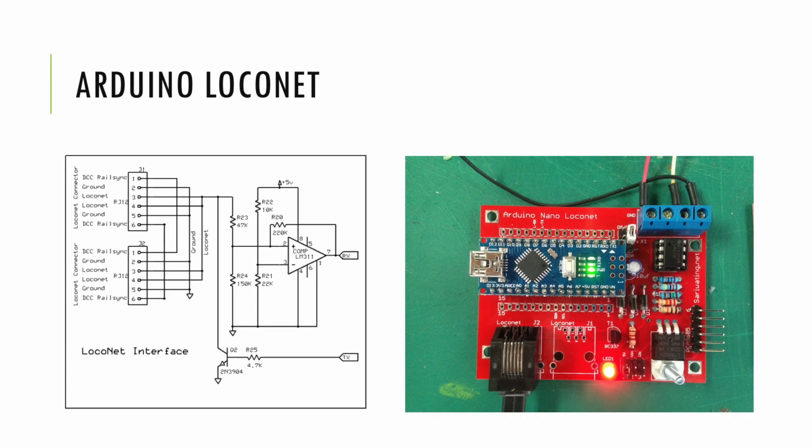We can easily connect an Arduino to Loconet and write some code that receives the occupancy detection messages from Loconet for the brake and stop sections, and in turn responds with Loconet control messages for the locomotive.